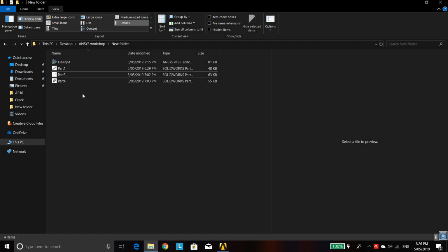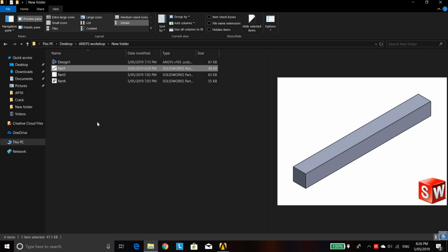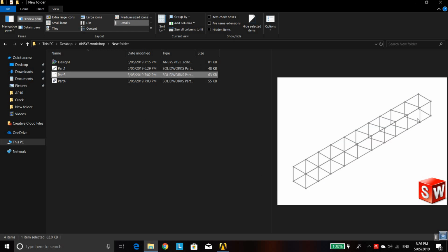So what I did, I started drawing those geometries in SolidWorks, as you can see here. This is a block of concrete I have, and then this is a rebar I'm going to put inside. As you can see, they're not uniform. I just drew some wire inside. These are just lines, so when I go into ANSYS, it is going to ask me to give some cross-sectional area for these. Okay, I'm going to do that later.